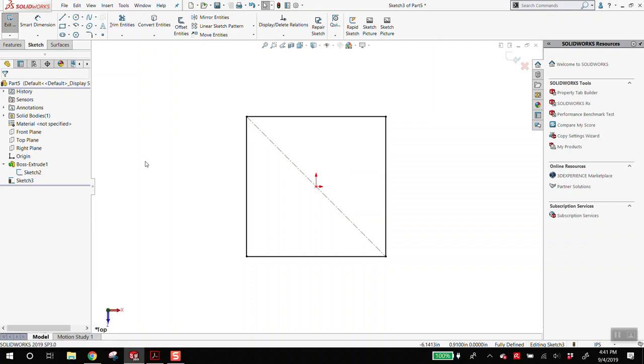Right. It's like a points to. It's a copy that is constantly pointing to the original. But it doesn't create the sketch itself. It first needs to create a new sketch. So you're in this sketch, you need to enter a new sketch to convert entities from this to this. If you're just in this sketch and you're not creating a new one, convert entities won't work. And it doesn't matter which position the second sketch is, like above the old one or below. You can only convert entities with sketches that exist before it.